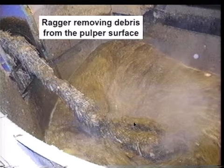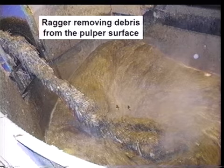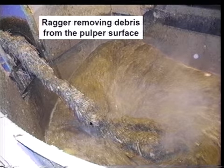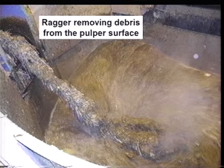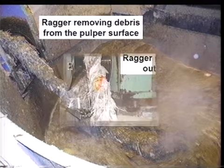Okay? Now here's the ragger. It actually is this thing right here. And you can see here's the swirling pulp from our pulper. And then the ragger is actually pulling this snake, and you can see that it's got wires and plastics and all kinds of stuff that we can't make into recycled paper. So this snake is actually being pulled out of the pulper in a continuous manner.